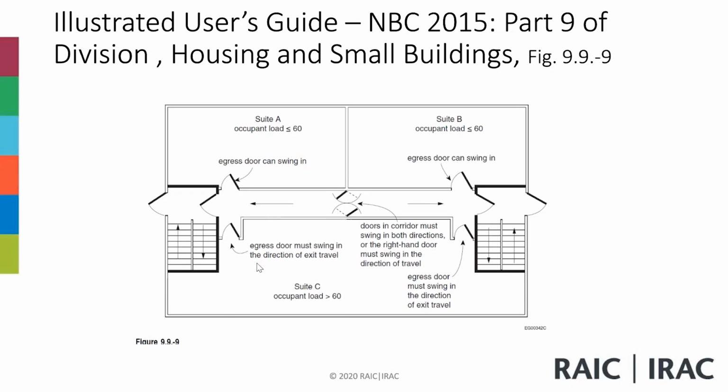It requires 2 doors, and both doors need to open to the outside. If you've got double doors in the corridors, they need to open in opposite directions, leading to the exit. So you see that exits all the time will have the door opening in the direction of exit, and here to the outside, you're going to the outside. So for the direction of swing of doors, whether for exits, for egress from roofs, or in the middle of corridors, there are provisions related to it.